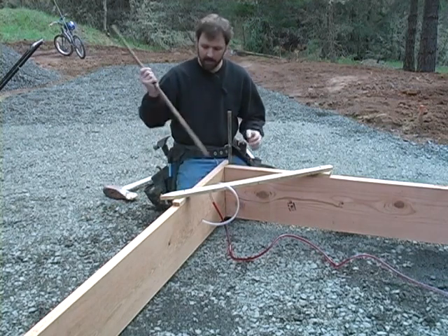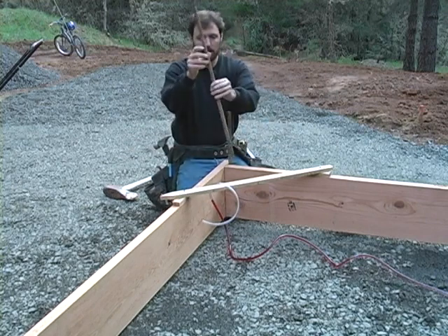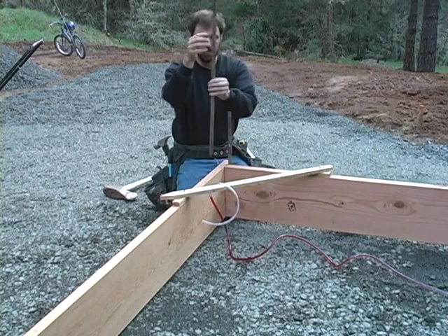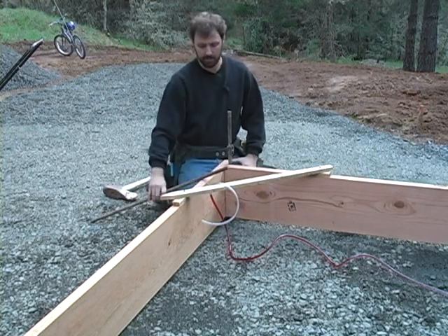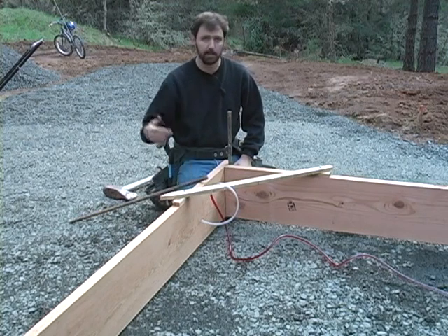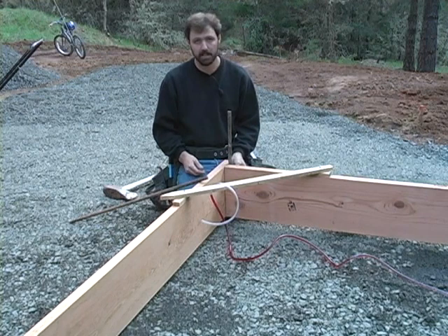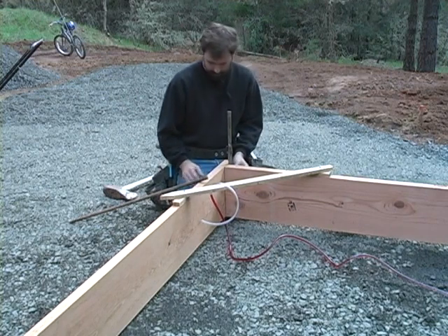Now this is a concrete stake. This is a 3-foot concrete stake, and it has little holes drilled in it in opposing directions. Now you drive these into the ground. They're easier to drive into the ground than the wood stakes. You can really bash them into some pretty hard stuff. And with the holes already in there, you can just put a screw right in. It holds it in place. When you're ready to screw the form in place, you just go and drive it right through.